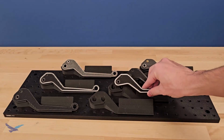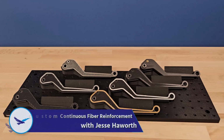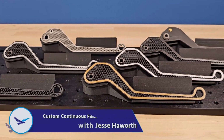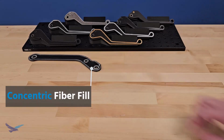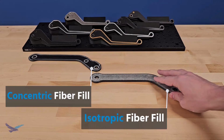This is Jesse Hallworth, Senior 3D Printing Application Engineer, and in today's video I'll be talking about a brand new software update from Markforged that will allow users to create fully custom continuous fiber groups anywhere in their 3D printed parts. Traditionally, fiber is inlaid into Markforged parts in either a concentric pattern along the walls of geometry, or in an isotropic pattern that fills an entire layer with continuous fiber.